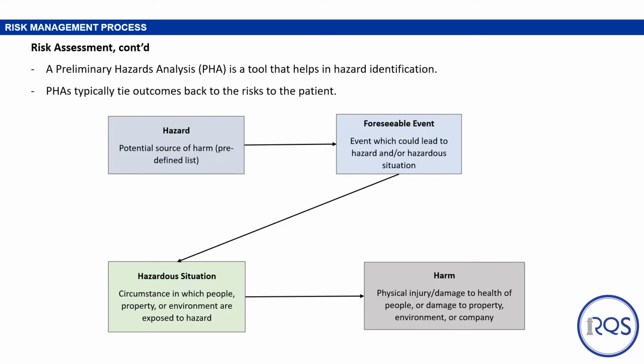During the PHA development process, consider and focus on hazardous components, safety-related interfaces between various elements of the system, including the software, environmental restrictions, and including operating environments, testing, maintenance procedures, integrated tests, diagnostics and emergency facilities, installed equipment, support equipment and training, and just any possible malfunctions that may occur with the system or subsystem.